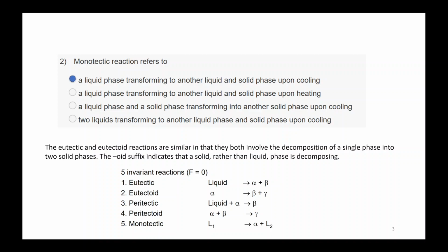UTS, yeah. When you try to explain why the curve is coming down, you say it's losing its cross section, so they are trying to balance. Strain hardening is occurring in the entire region up to the fracture point.